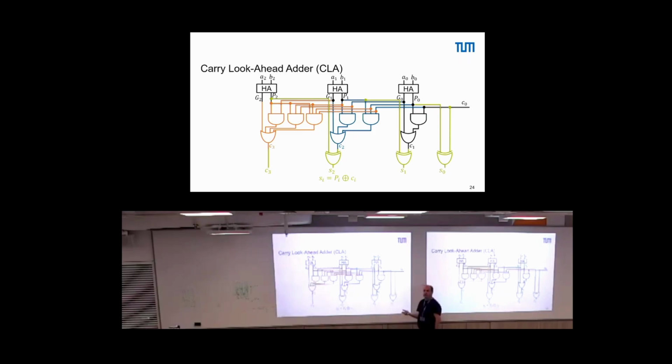That we commonly call fan out. So the fan out here is relatively large. So we have 2 effects. We have not only a larger area compared to the ripple carry adder, we also have a larger fan out, which means we see the capacity of more wires plus of more gates.